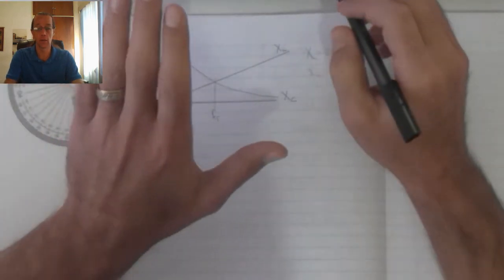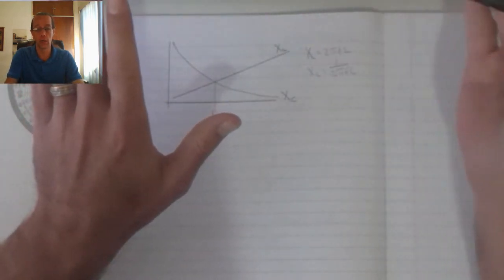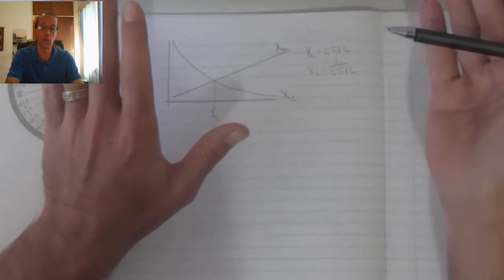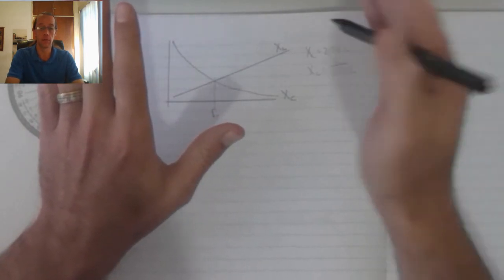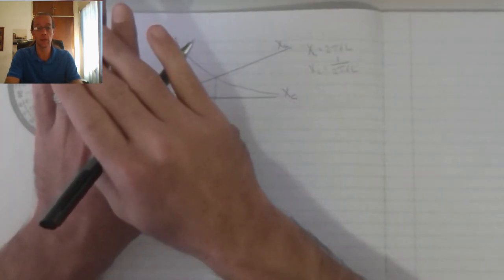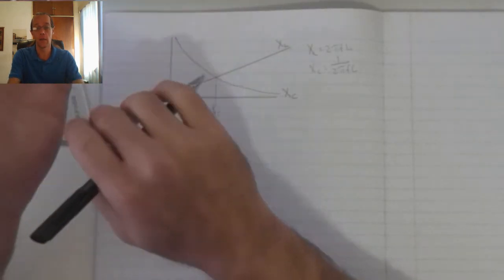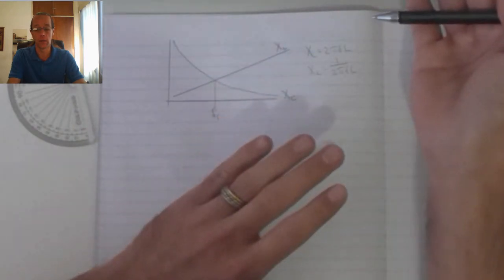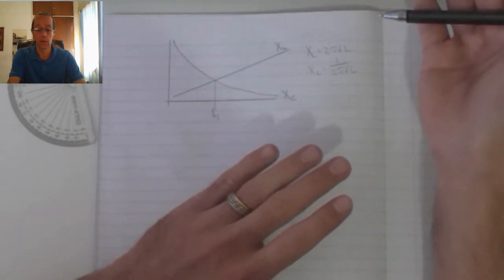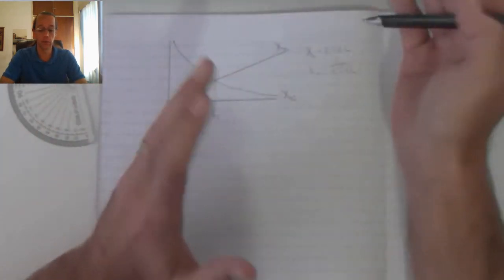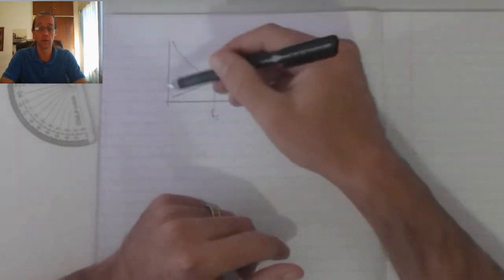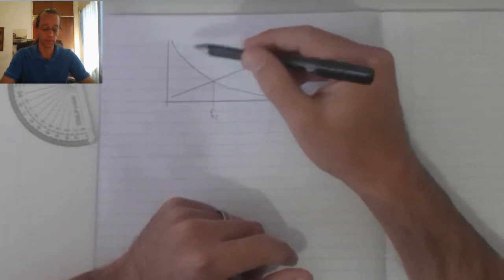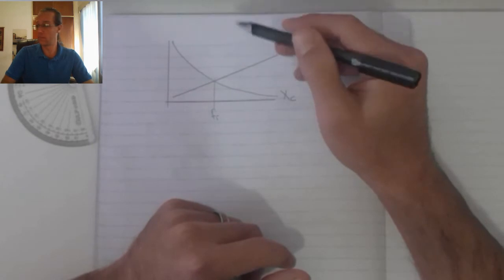So, as the capacitor charges, the inductor is losing its stored energy and transferring it to the capacitor, and vice versa. The capacitor discharges and that energy is transferred into the magnetic field of the inductor, and that causes very little energy to actually be transferred from the supply.